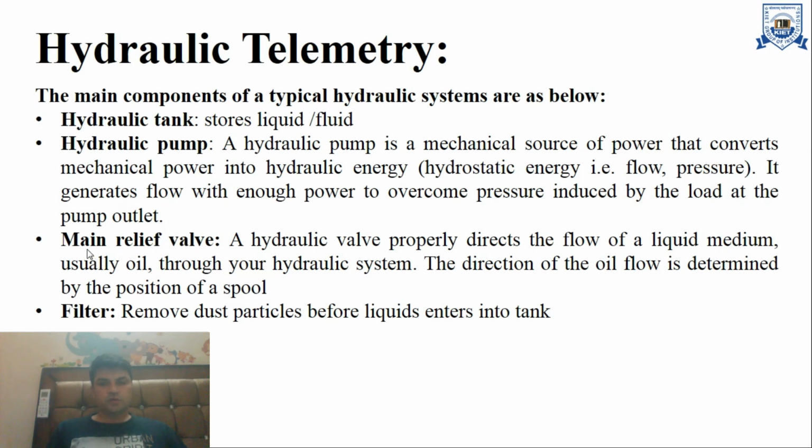The next part is the main relief valve. A hydraulic valve properly directs the flow of a liquid medium, usually oil, through the hydraulic system. The direction of the oil flow is determined by the position of the spool. Here is the lever. It can change the direction of flow. Next is the filter. It removes dust particles before the liquid enters the tank.